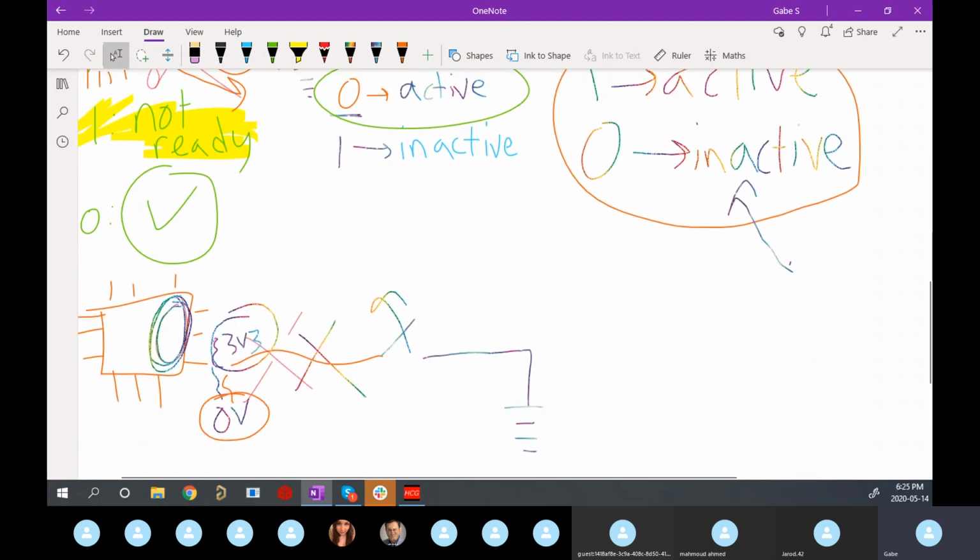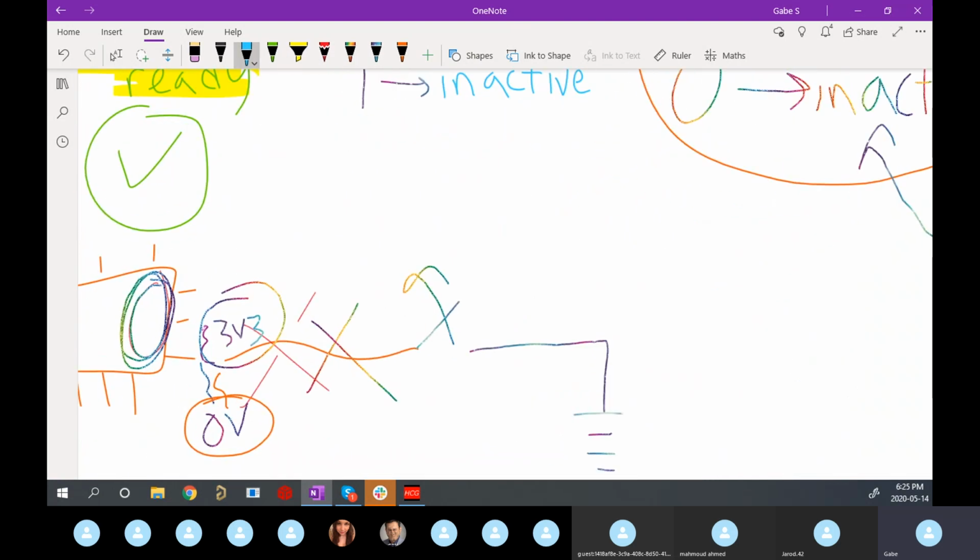Okay, this drawing's messy. Let's go to this one. So if you have your internal one configured, right, that's great, but sometimes people also just put one on the outside as well, in the actual hardware on your circuit board. And common values are 10K, 10 kilo ohms, right? And that just adds an extra layer of redundancy just in case something goes wrong in your software. So this is a really common practice.